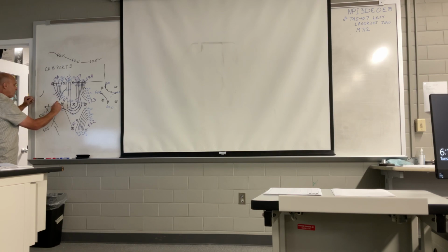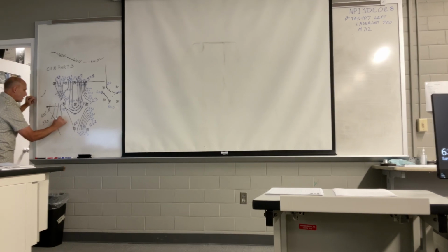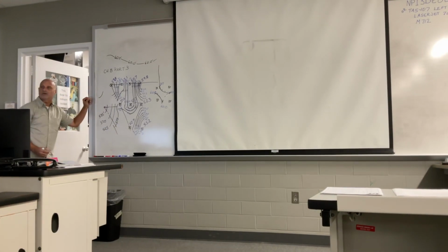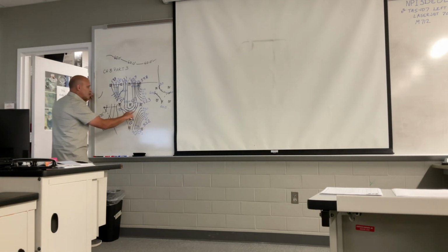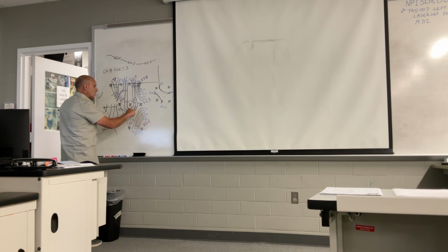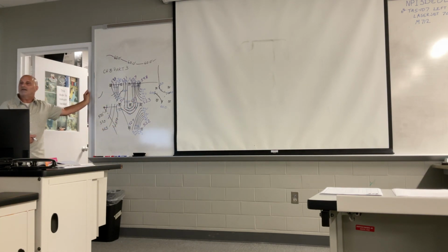And then I had this 52.0 that was going a little bit lower, so maybe I'm gonna take that one and put it out here in the middle because that contour is a little longer. We need to be able to stick our finger out there and say, what's the elevation of this contour, and be able to go in a little ways and find that elevation written. Now, I recommend you do it with text masking. You do your multi-line text and you use text masking.